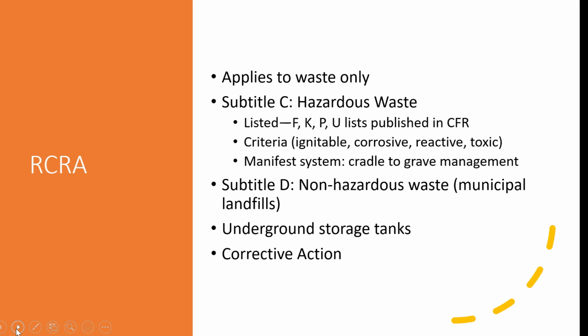Hazardous waste is defined in the statute as two different kinds. There's criteria waste, waste that is always hazardous because of its characteristics. The four characteristics are on the slide: ignitable, corrosive, reactive, meaning that it's likely to explode if exposed to air, to oxygen, and toxic. So if something meets one of those four criteria, it is a hazardous waste governed by